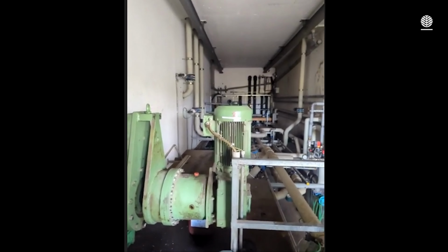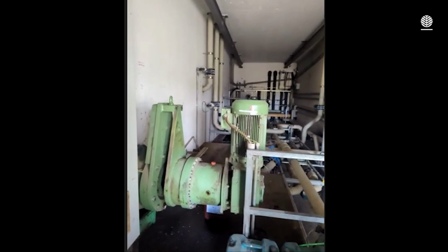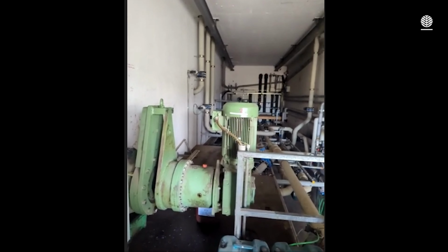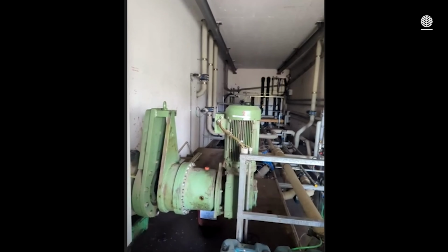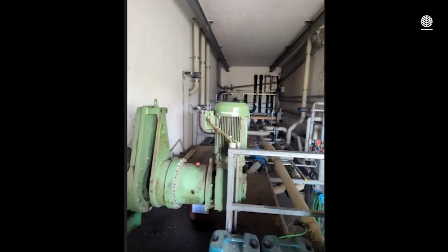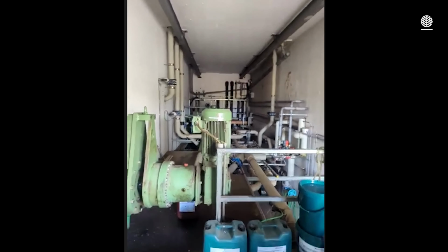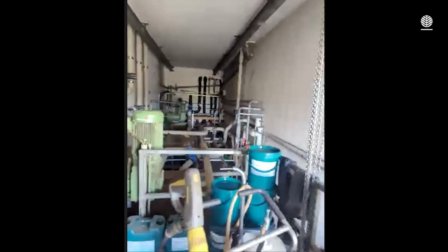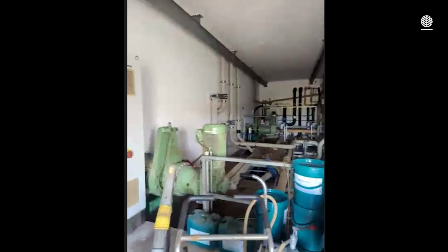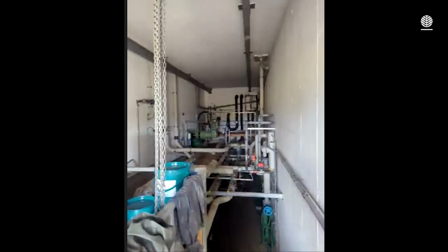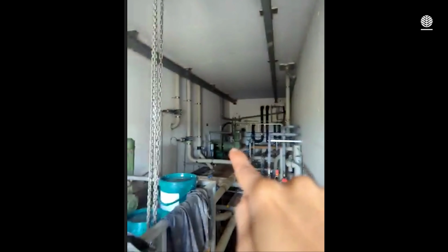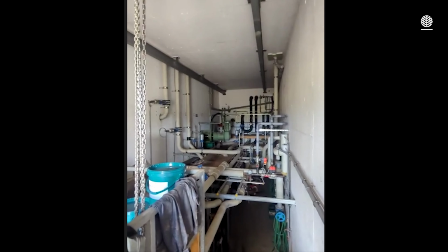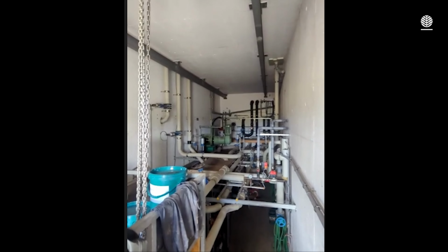And here you can see the drives from the agitators. It's 18.5 kilowatt performance, and the speed is 5 rotations per minute. So if you walk a little bit to the side, we can see the other agitator drive in the back, the green part. And on top we have a crane to lift them out. Yeah, there's another one, and it's open. The digester is rectangular. It's open, like we've seen in the very beginning on the drawing.